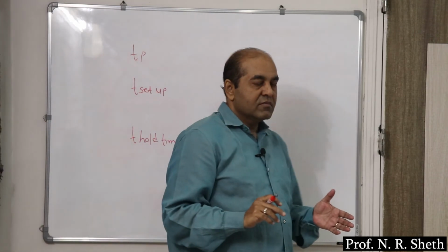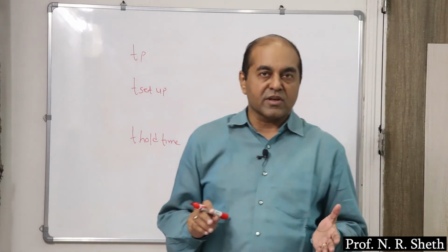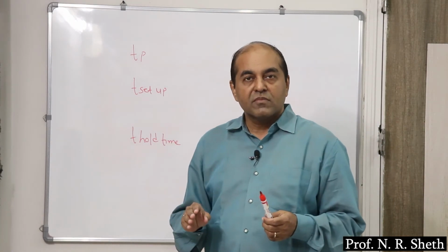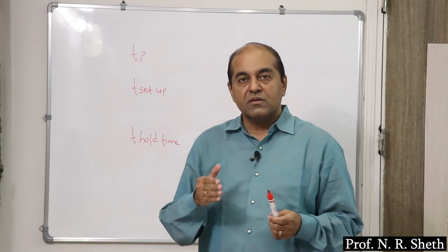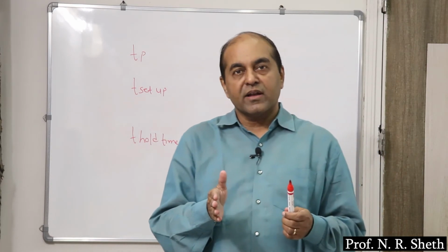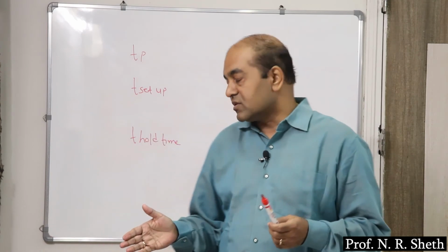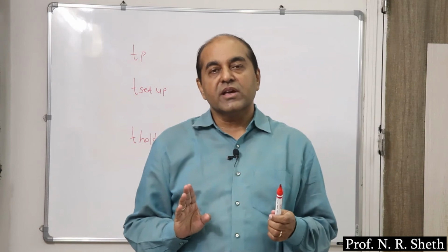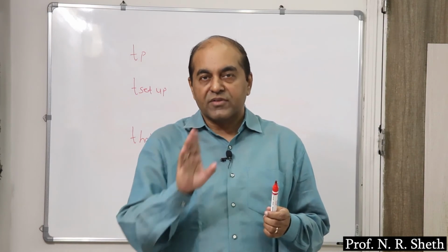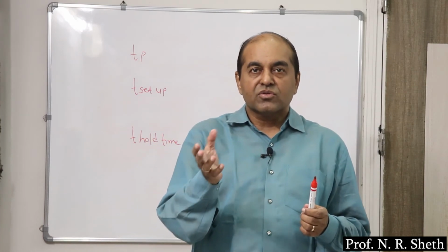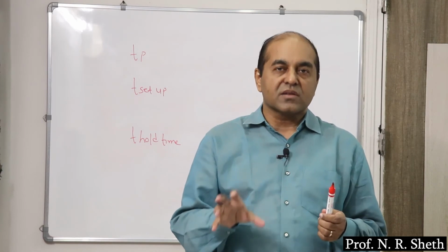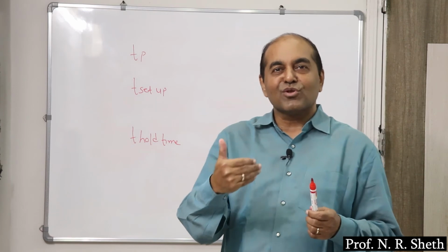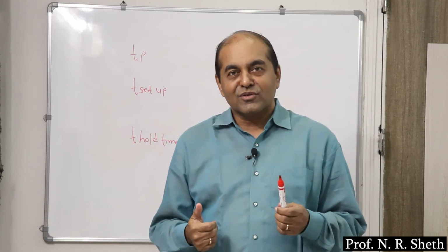The time before the clock pulse arrives, data must be present, is setup time. Hold time means the data should be there even after the clock pulse arrives, and the time required to change the output after the clock pulse arrives, so the internal time consumed by the circuit, is known as delay time. So, this timing is also connected with you.